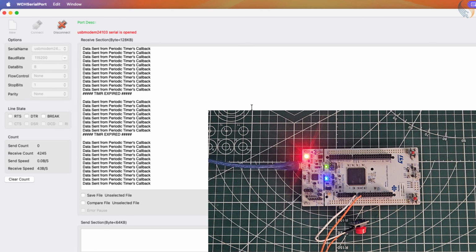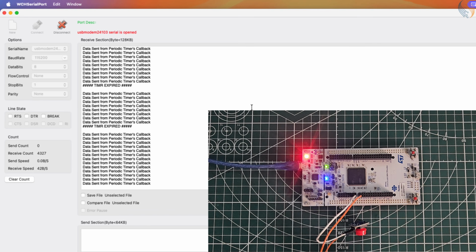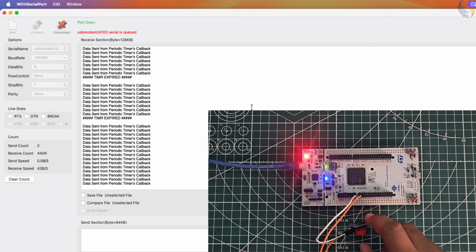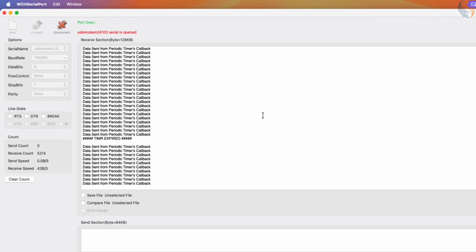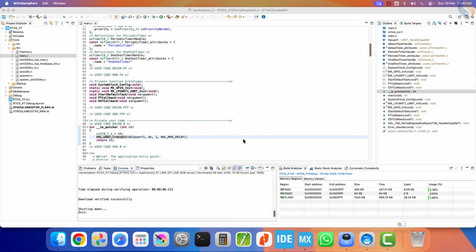Every time the button is pressed, the timer start function is called again for the one-shot timer. This does not create a new timer or stack multiple timers on top of each other, it simply resets the existing one, pushing the expiry point forward by another 5 seconds from the moment of the latest press. As long as we keep pressing the button within the 5-second window, the timer keeps getting reset, it never expires, and the callback is never triggered.